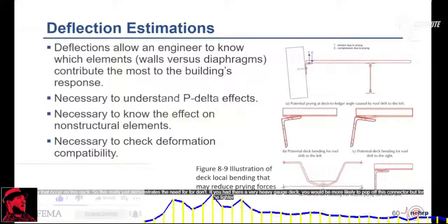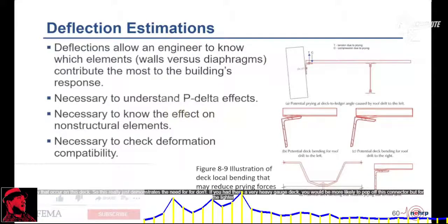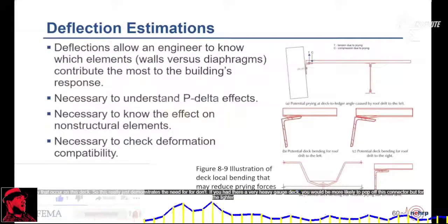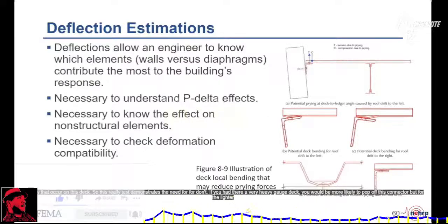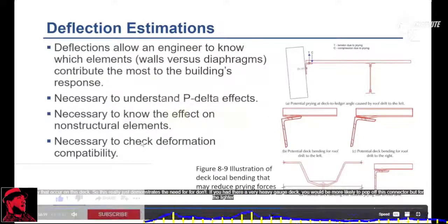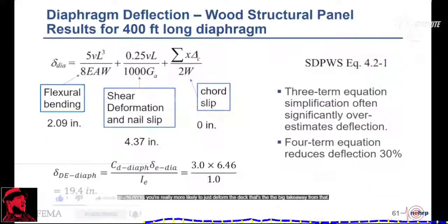So this really just demonstrates the need... if you had a very heavy gauge deck, you would be more likely to pop off this connector. But for the lighter gauge decks, you're really more likely to just deform the deck. That's the big takeaway from that.